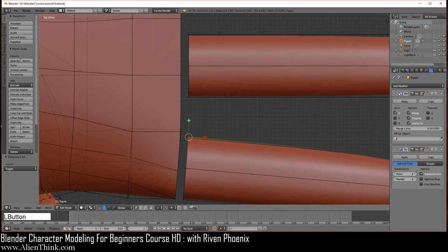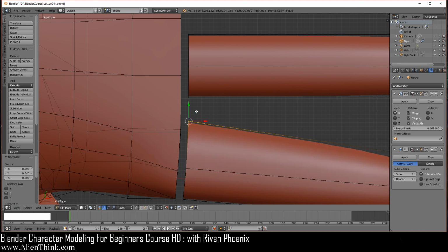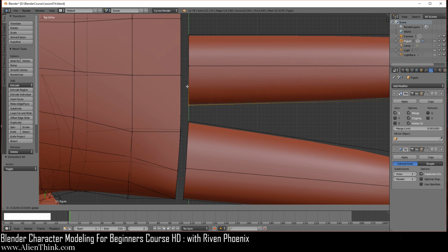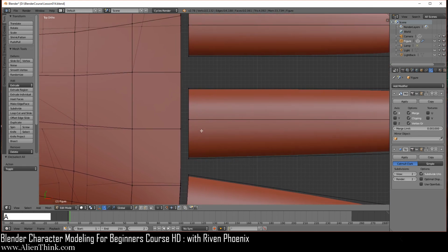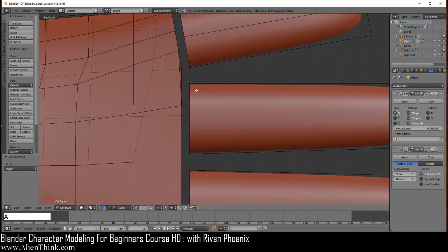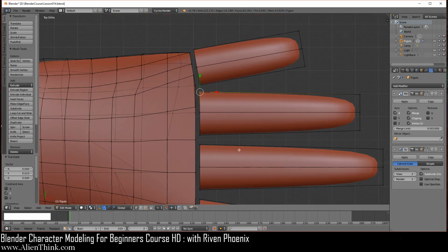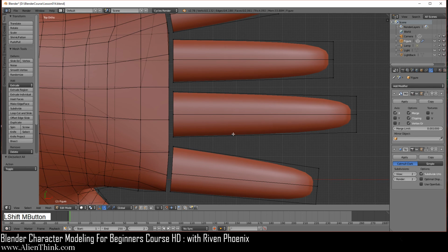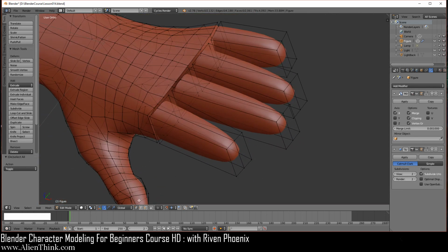We're going to bring this up 1, 2, 3, 4, A to deselect, press on this one, C, and 1, 2, shift middle mouse button to pan, A to deselect, press the C key, select it, right click to get out of it, do 1 and then 2, A to deselect, press on the C key, click on it, right click to get out of it, 1, 2, shift middle mouse button to pan, A to deselect. Now on this one, when you select it, just bring it up only one time over here and then A to deselect.